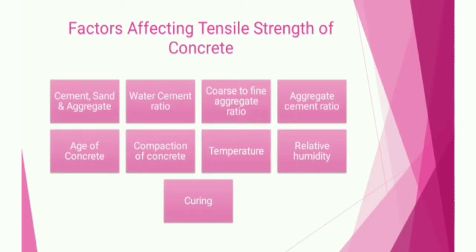Age of concrete. The degree of hydration is synonymous with the age of concrete, provided the concrete has not been allowed to dry out or the temperature is too low. Compaction of concrete. Any entrapped air resulting from the inadequate compaction of plastic concrete will lead to reduction in strength.